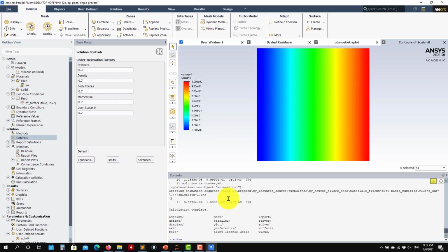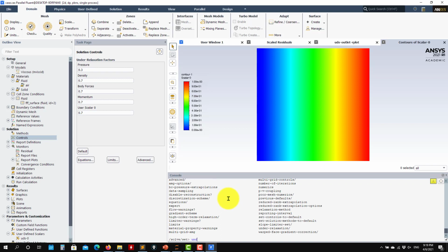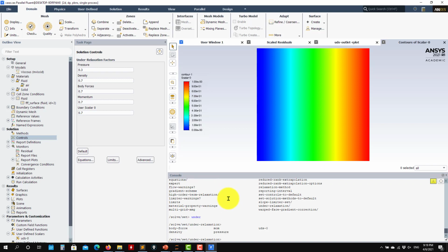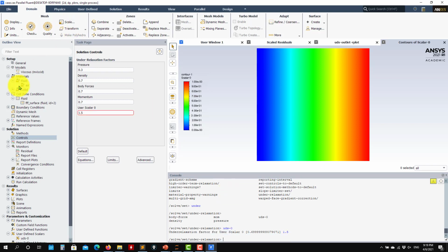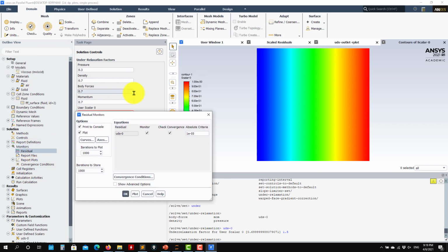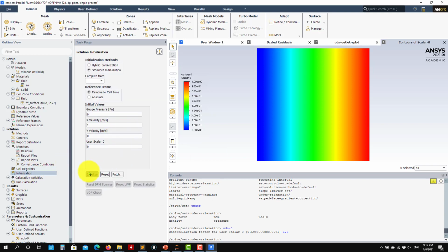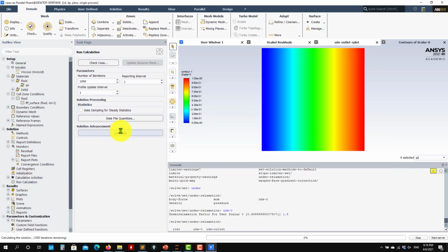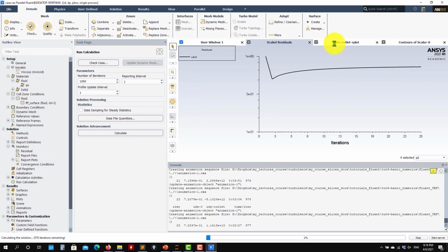But just to show you, you go Solve, Set. You have there under relaxation, and I want to change this under relaxation. Let me put there 1.5. See that now it will take it. Let me go back here, initialize, and let me run this case. See that now Fluent is divergent.